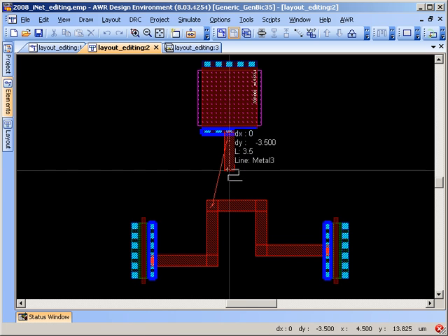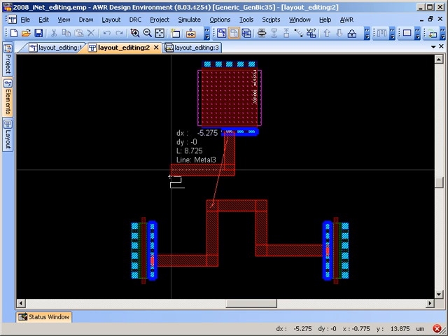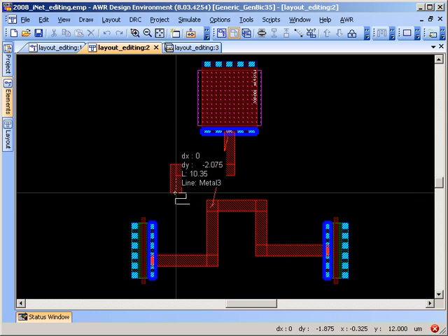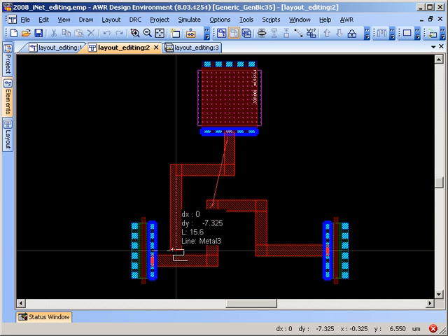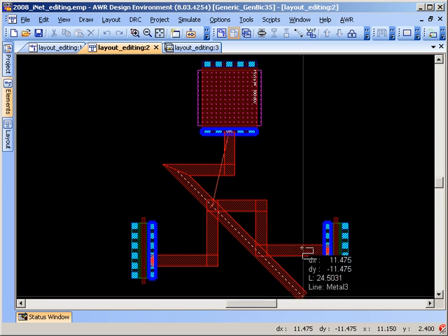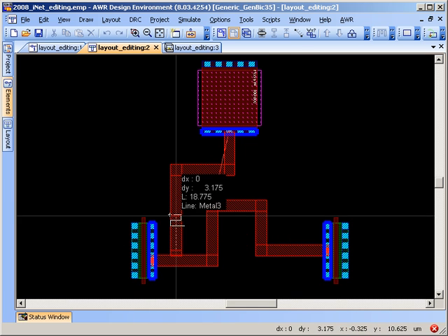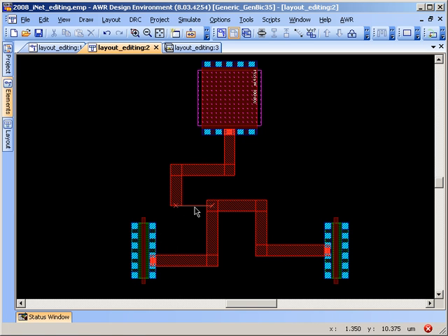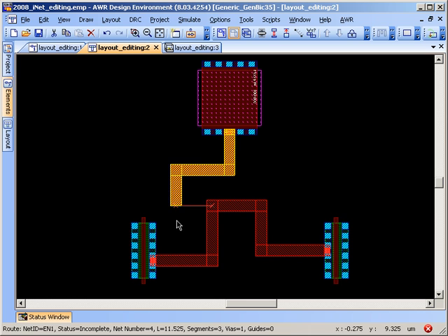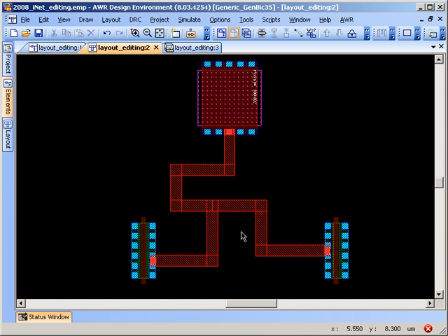And if I route from the resistor, you'll see that as I move down, I'll add a point here, and then as I move down, I get a snap point here, a snap point further down, coming from this line over here. So lots of snap points from any existing routes that are on the same electrical net to help me get the routing aligned perfectly and snapping perfectly.